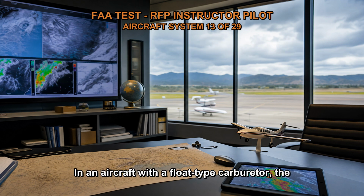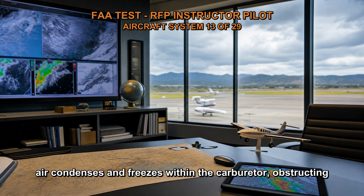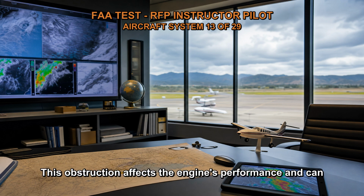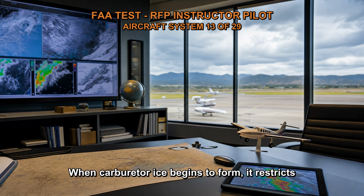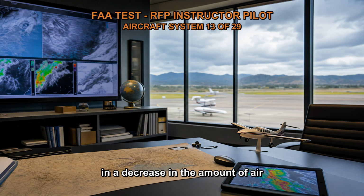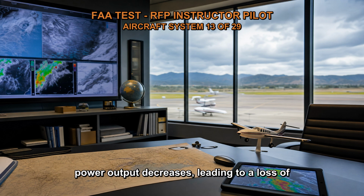In an aircraft with a float-type carburetor, carburetor ice can develop when moisture in the air condenses and freezes within the carburetor, obstructing the proper flow of air and fuel mixture. This obstruction affects the engine's performance and can lead to a loss of power. When carburetor ice begins to form, it restricts the airflow and disrupts the fuel-air mixture, resulting in a decrease in the amount of air reaching the engine cylinders. With less air available for combustion, the engine's power output decreases, leading to a loss of RPM.